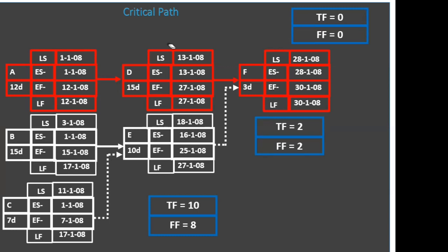Right. Now see. If you are facing network problems, you can watch this recording later, and you'll get to know. I'll show you again on the software, don't worry. So these were the activities for which we have made the forward pass and backward pass. We have found the total float, free float, and all those things. So you can see these activities which are highlighted in red color have total float equal to 0. That means these activities are critical activities in your project.